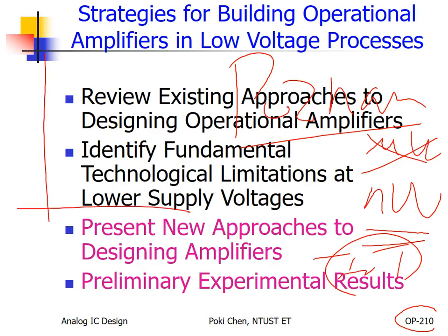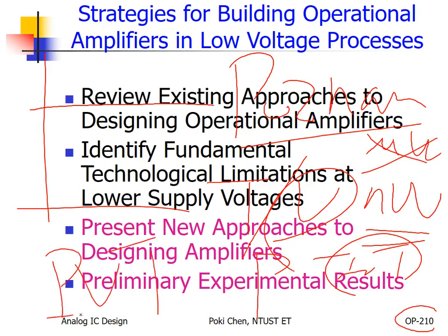Anyway, for reference voltage, it should be stable according to temperature. Not only temperature, but also hopefully supply voltage. Never mind what kind of supply voltage, what kind of temperature, you still provide the same output voltage. That is what we want, according to process variation. So PVT, process voltage temperature variation, hopefully they don't cause any harm to your output voltage. That is for the ideal bandgap reference voltage. But to be honest, it's really hard.